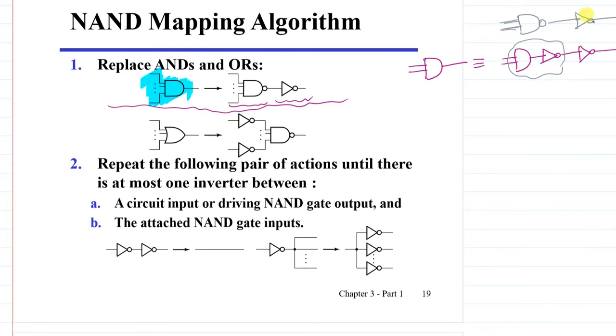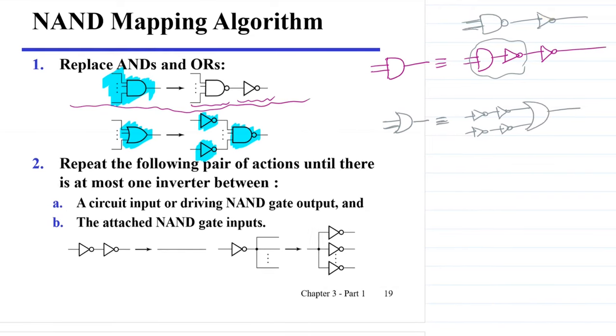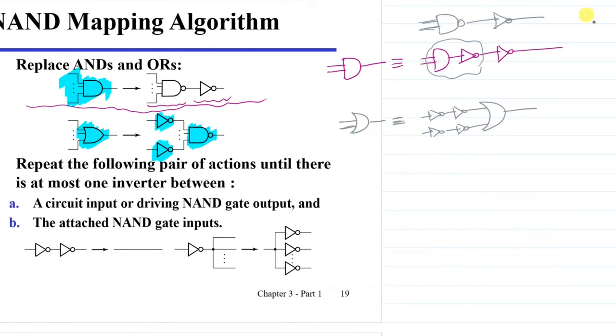On the other hand, for the OR gate, we can do it in this form. If you have the OR gate with a given number of inputs, we can replace it with a NAND gate and add inverters at the input side. It's obtained following this. If we have the OR gate like this, assuming 2 inputs for now, we can add 2 inverters one after the other for each input, and we know that these are equivalent because 2 inverters one after the other cancel each other's effect.